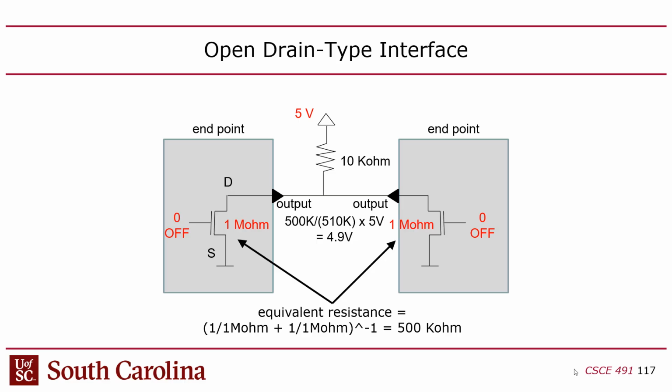it will be a small drop because this becomes a voltage divider and the wire becomes the midpoint of the voltage divider, and the resistance to ground is very high, in the mega ohms. So you end up with a voltage divider where on the high side you've got like 10 kilo ohms, and on the low side you've got mega ohms, or hundreds of thousands of ohms.